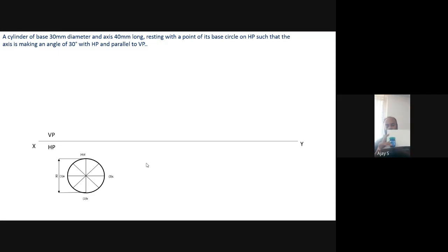Now in front view, how will it look? It should look like this. Centers also I have marked. Since the one on top will be O2, that will be visible, and O1 will be hidden. I have marked O1 in bracket and O2 outside. Okay. So this thing I'll just project it, and I mark the outer points. Since it's the top view, I have told this is 1, 2, 3, and 4. 2 in the front and 4 will be behind. So when you view like this, it will be 2 dash bracket 4 dash, right? Over here bottom, 2 dash bracket 4 dash.